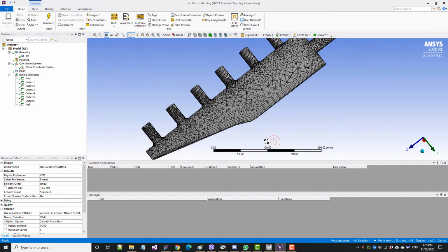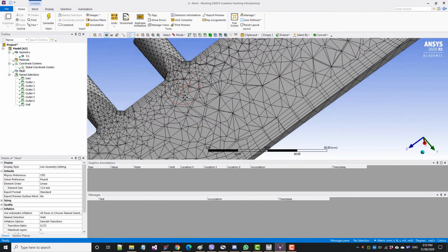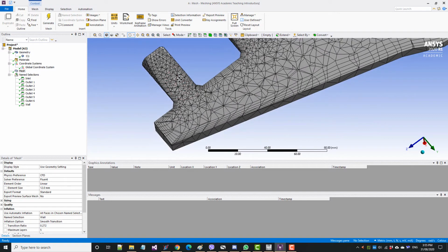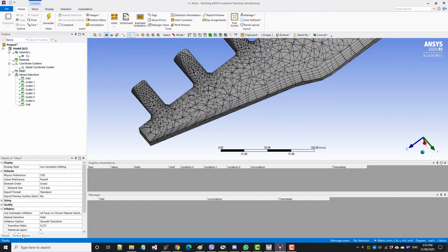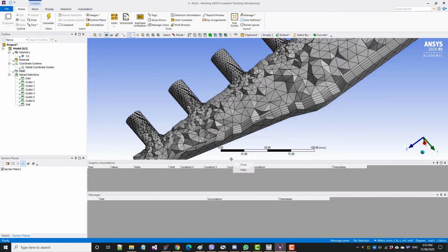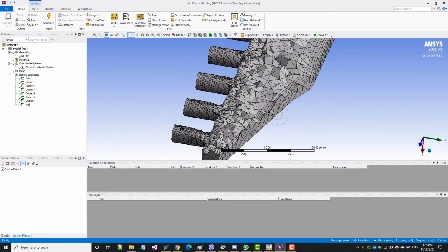geometry. Rotating my model to expose a section plane, I can see the intersection of the mesh with the section plane. To make things clear, I will click here on the Section Plane panel. This icon will enable Show Whole Elements, and you now can see the prismatic elements created on all walls, running through the inlet as well as the 6 outlets. You will learn more details about inflation later in the course.